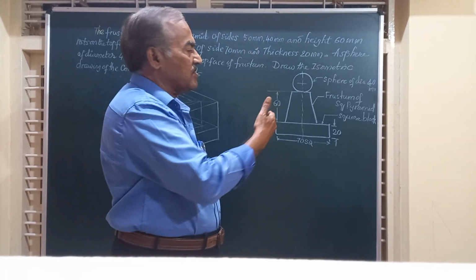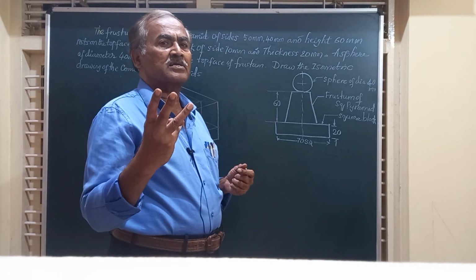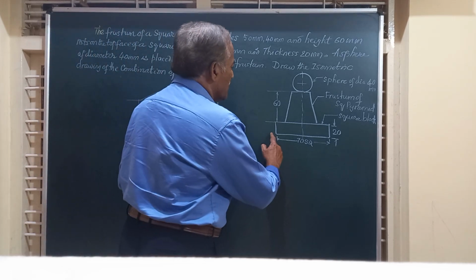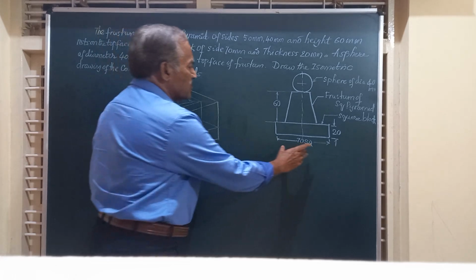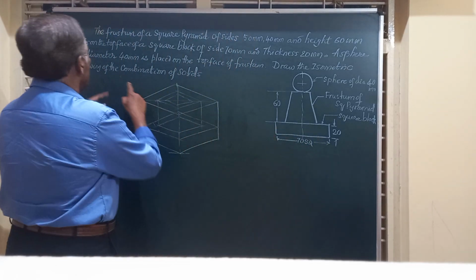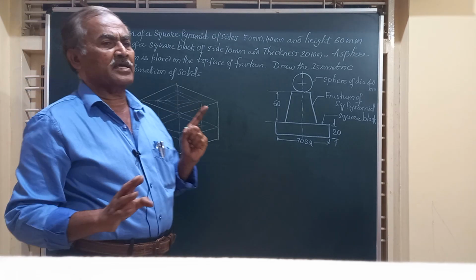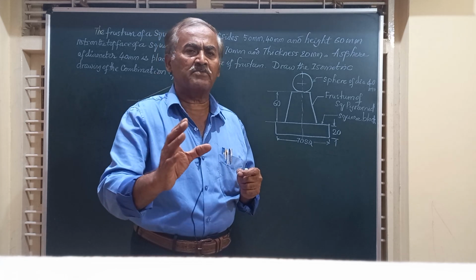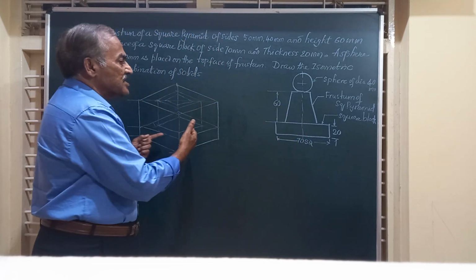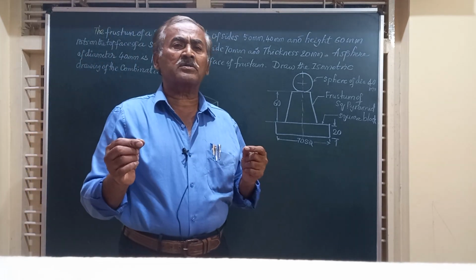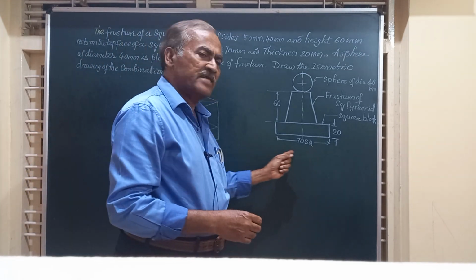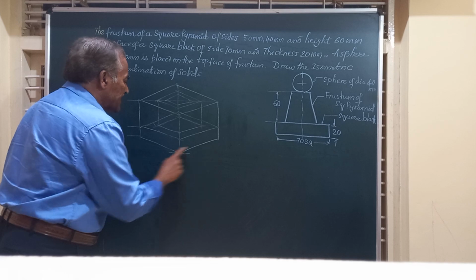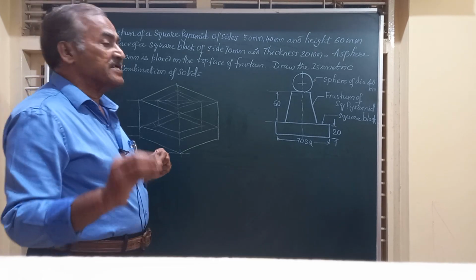In fact, it consists of the solution for the isometric drawing of three different solids. Friends, let me start this problem with the square block, which has a dimension of 70 millimeter. When I say it is an isometric drawing, you have to take the actual dimensions, and the figure is drawn to a scale of 1:1. Whatever dimension you have here has to be transferred onto lines which are inclined at an angle of 30 degrees to the horizontal.